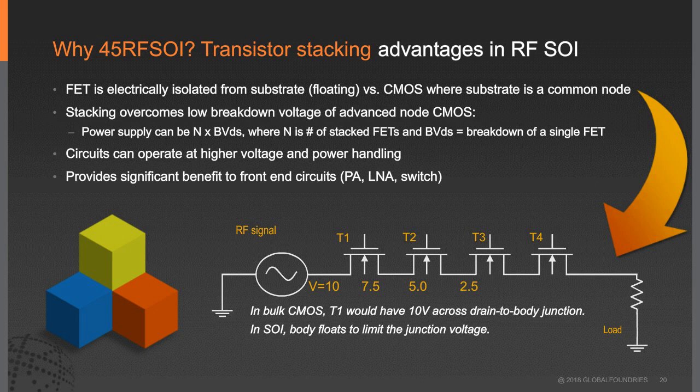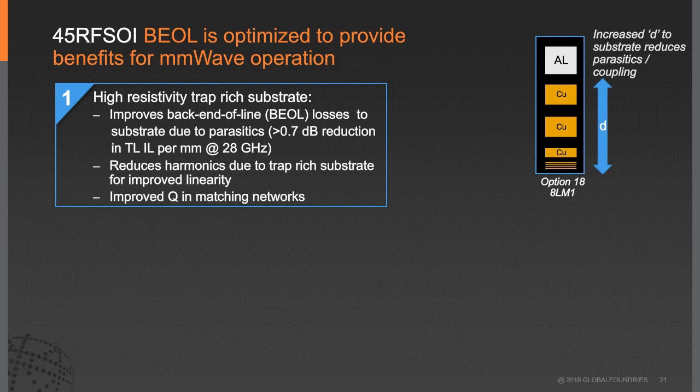Going back to the figure of merit, you want the most efficient power in RF, and that's what you're getting: a very high power added efficiency of 43% at a very high output power, 23 dBm, in our demonstrator circuits. So that was on the transmit side.